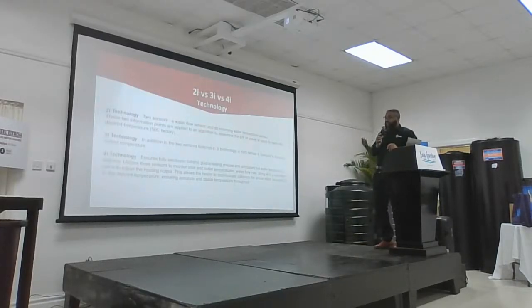So the 4i technology, this is what is in the DC Premium models, ensures fully electronic control, guaranteeing precise and consistent hot water temperature and delivery. It utilizes three sensors to monitor the inlet and outlet temperatures and water flow rate, along with a motorized valve to adjust the heating output. This allows the unit to continuously compare the actual water temperature to the desired temperature, ensuring accurate and stable temperature throughout.